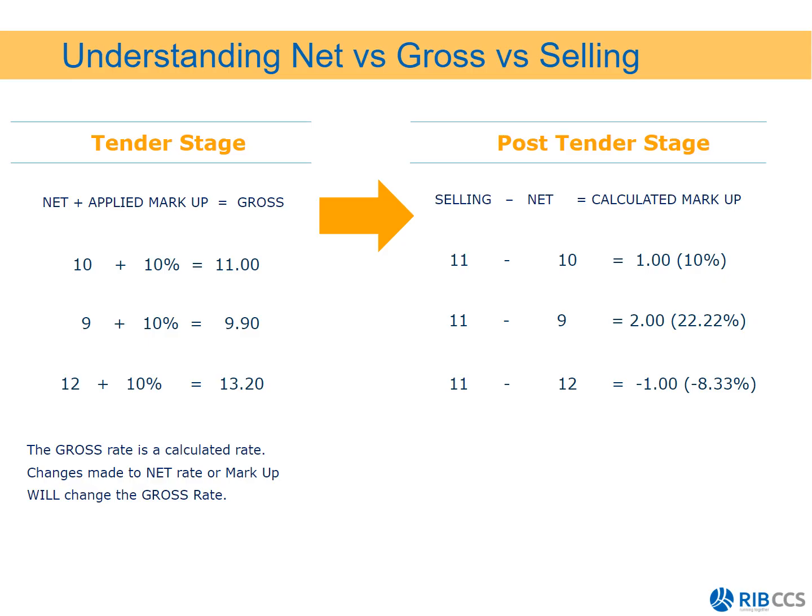And the nice thing then is we can go and play around with our worksheets. So the site team might say we can do better buying, we can do better production, and therefore this item is only going to cost us 9 per square to do, for example. So 11 minus 9 means that you're making 22.22% profit on this item now. Therefore, you are managing the project using Candy and utilizing it to make additional money, etc.